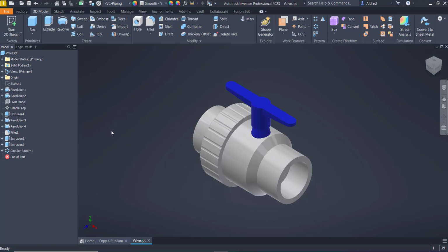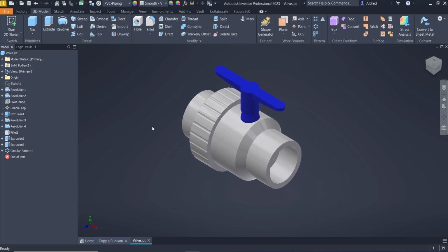In today's video, I'm going to show you how to take a part that you might have received from a company's website, maybe a client sent it to you, or you just found it in an old AutoCAD drawing somewhere, and use it as one of the fittings that you can do in Inventor Tube and Pipe. So the first thing we need to do with a part that you have is author it, and then you can publish to the Content Center, but you don't necessarily have to.